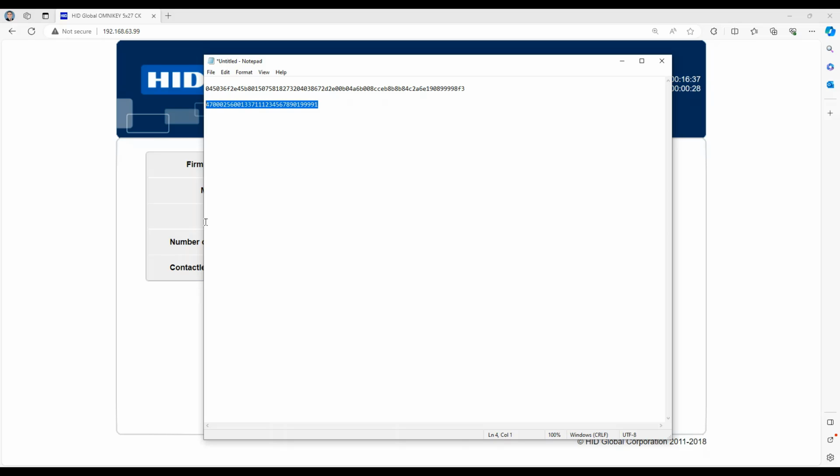Depending on how you have the system configured or what kind of card format you're using in the access control, you will need to trim this number down to read a certain portion. I like to switch this to maybe 75-bit because of the different types of readers that you can use out in the field. So if I have a 200-bit reader, I'm going to read that and then just select a 75-bit portion of that number.